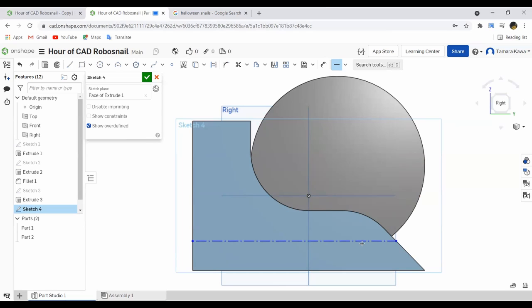So the reason I'm emphasizing this tree is because in CAD, we often like to work with relations rather than dimensions, because that is a better reflection of your design intent. Maybe I have a line that might be half an inch long or an inch long, but it needs to be horizontal. I can put in a horizontal relation, and no matter what dimension I make it, it will stay horizontal. So we're going to be going into that a bit more today.